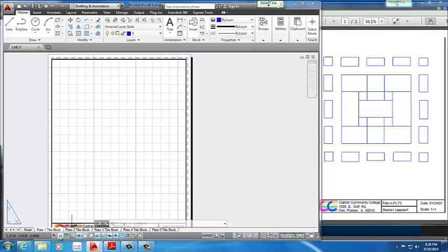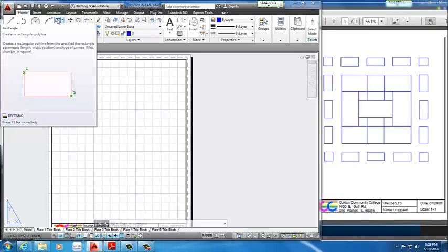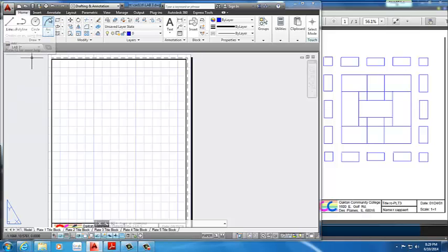So I also have, in case, my snap mode icon on. Go to Save as, and I'm going to go back into your H drive, your CAD 116, and call it your Lab 2. And if you want to save an older version of AutoCAD, you can do that right there. Change it to 2010. Save. It actually explains it better than me.